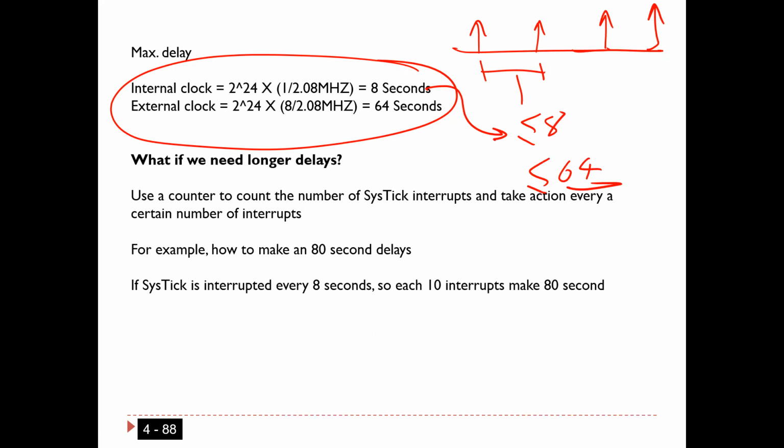I'm sorry if we already went over this in a previous class, but if we're going to keep the SysTick handler in that C file uncommented, should we get rid of the one in main? Yes, because in the C language you cannot define two functions with the same name. So you have to delete the one in main. Otherwise, the C compiler is going to give you an error, a double definition of a function.